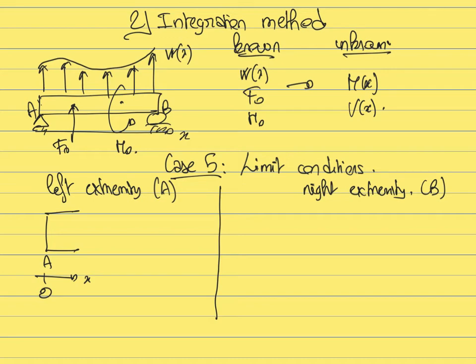So in this case, what I'm going to assume is that there's going to be a shear force that I'm going to write VA, and a moment that I'm going to write MA that are applied to the beam at the point A. I'm going to write them with the positive sign convention for the internal shear and the internal moment.